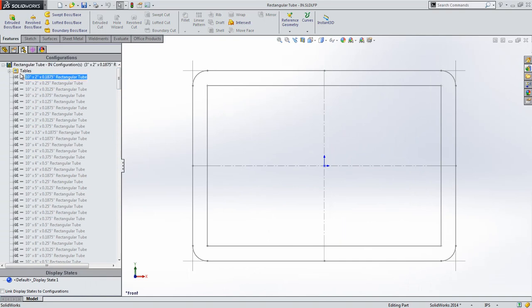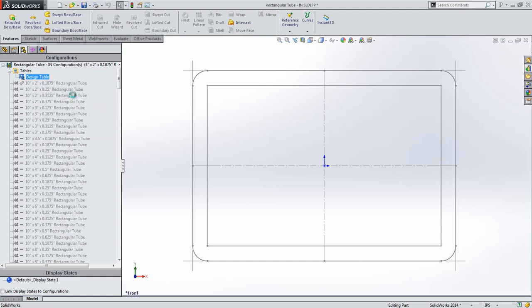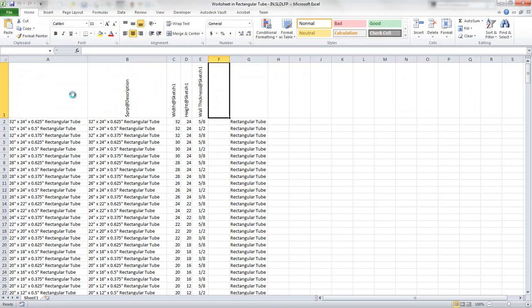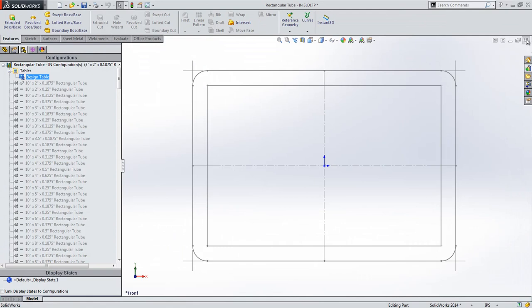To further benefit from this, all of these profiles can be created and maintained using powerful design tables to rapidly create all of the different sizes. This is done leveraging simple Microsoft Excel concatenation and speeds up the entire process of creation drastically.